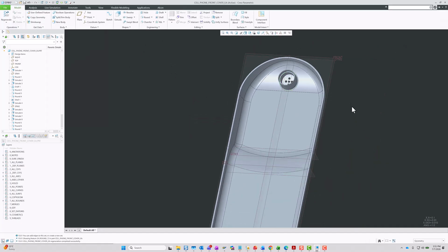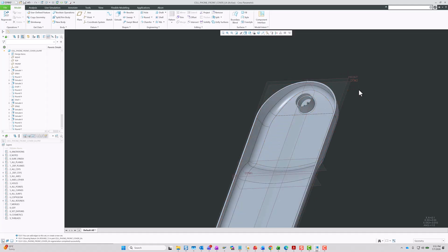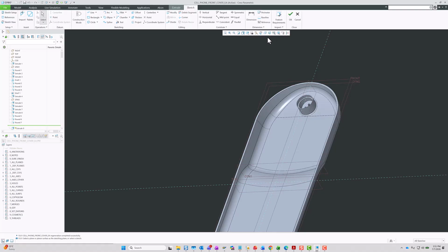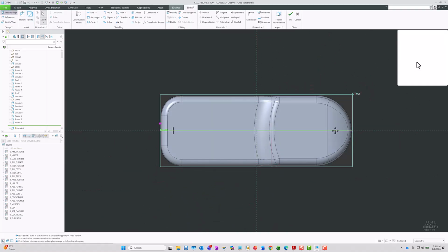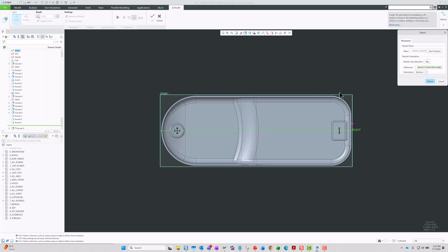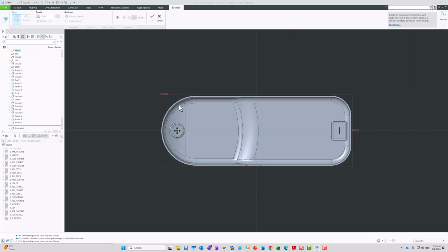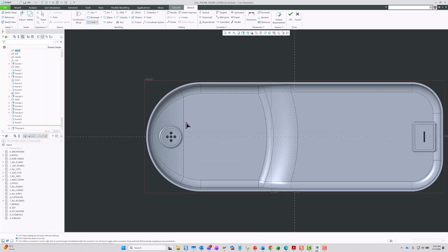All right. Okay, so the next step is to add the posts. So I will select this plane again. I will add an extrude, and let's place the position like this. You want to keep it. Sketch. And I will add a circle here, another one up here. The diameter will be 0.15. This dimension will be 0.4, 0.4. This will be 0.5.